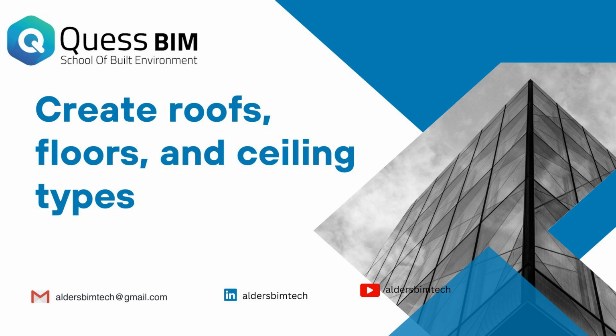In this video, you'll learn how to create and edit compound element types. And more specifically, you'll create a wood joist floor type with a carpet finish and define the layer materials and thicknesses. You'll then see how to slope elements using the sketch tools as well as the shape editing tools.